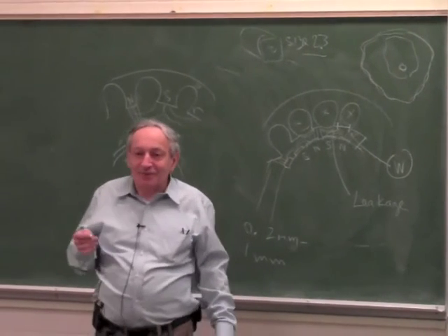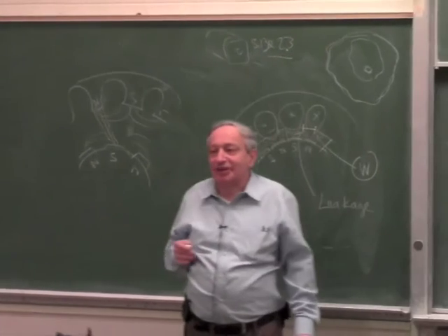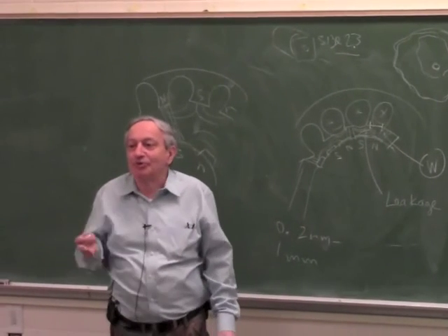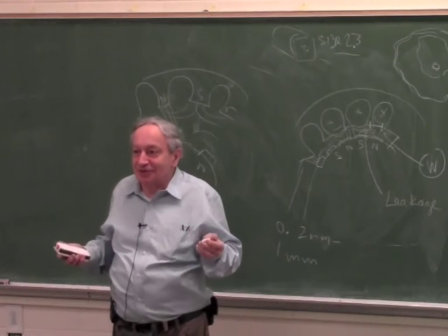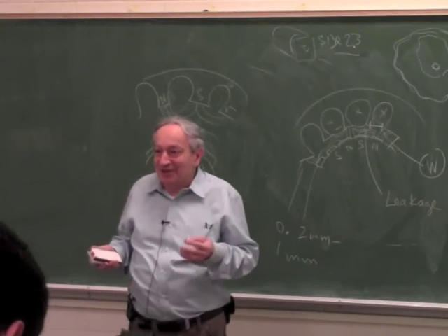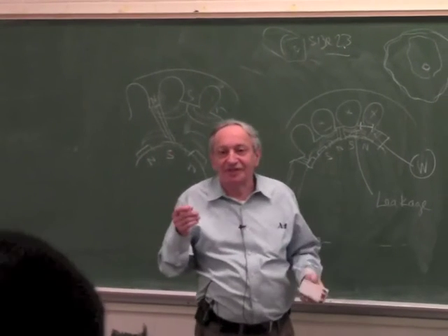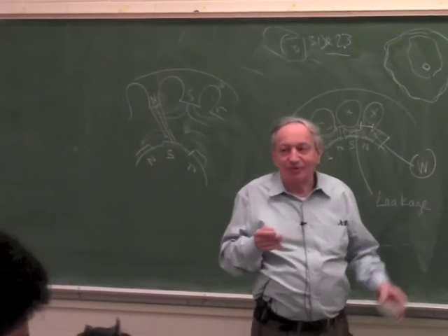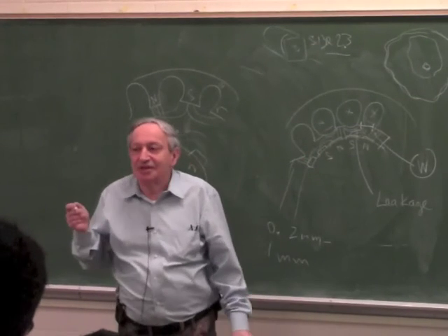So when you try to debug it, if something is truly closed loop, you have a much wider range of possible problems, like oscillations. If you have open loop, you cannot have oscillations. It can either move or not move, that's all. So if it doesn't move, you find out why. But it's a very simple system conceptually. It cannot have very strange behavior. While if you close the loop, there could be very strange things which take you a long time to figure out. A good example is backlash.